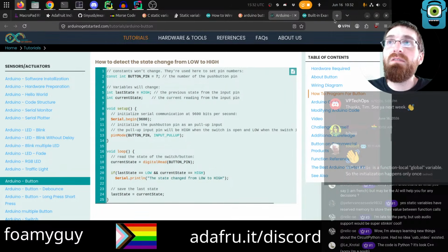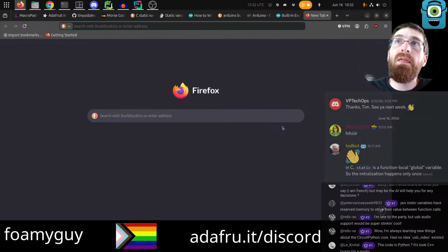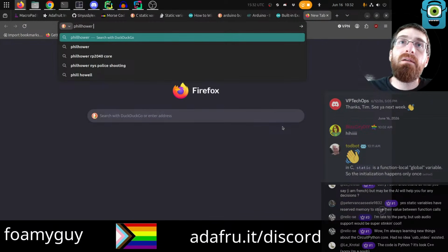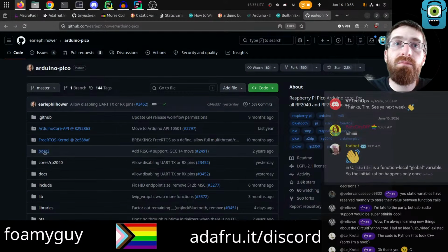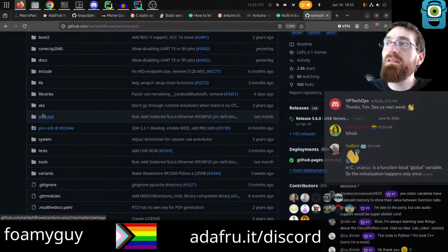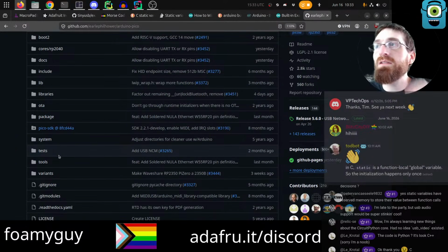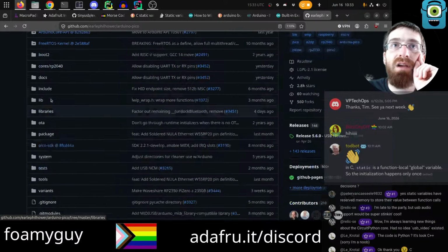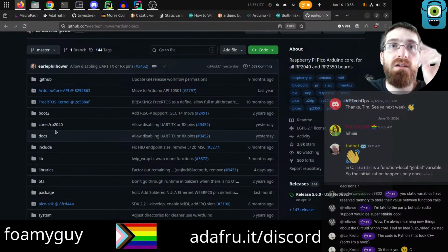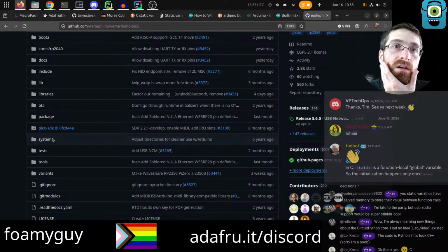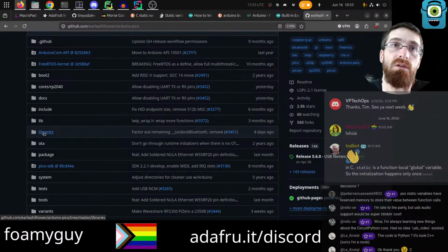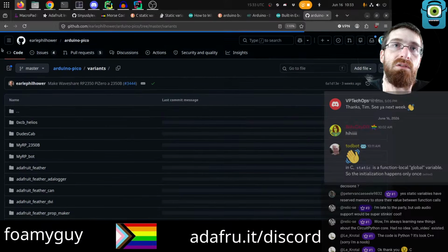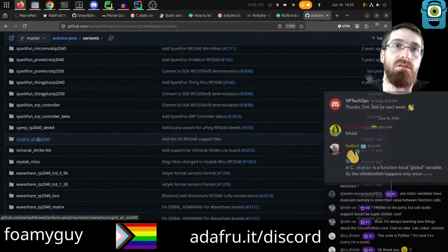So I do need the pin. Pins on the macro pad. I should say, if anyone is interested in replicating this, I did have to add board definition to TinyUSB for the macro pad, so if somebody is like actually trying to do this on a macro pad specifically the same way I am, you'll need the board definition files. I could give them to you, but let me know. Get this. Where does this go? It's in variants RP 2040.